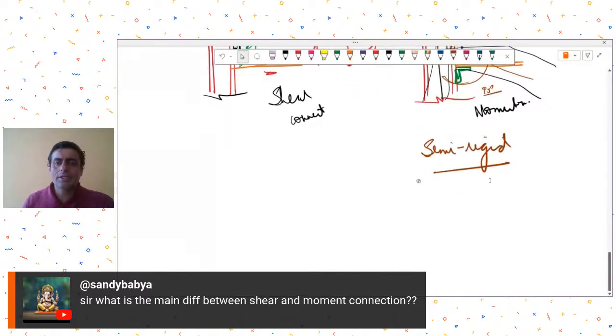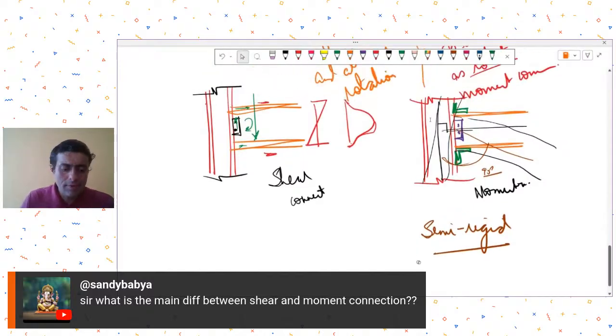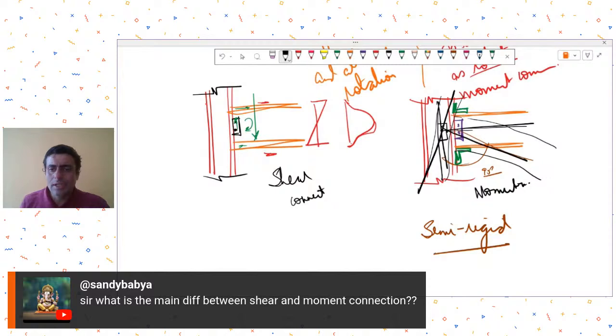And in connections where the relative rotation remains the same after displacement, that means before the load application the angle was 90. After the load application the system rotates, but the rotation is such that the relative angle still remains the same. Those kinds of systems I call rigid.